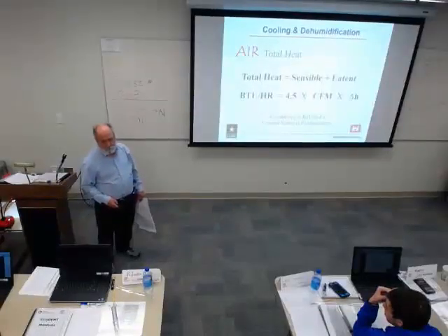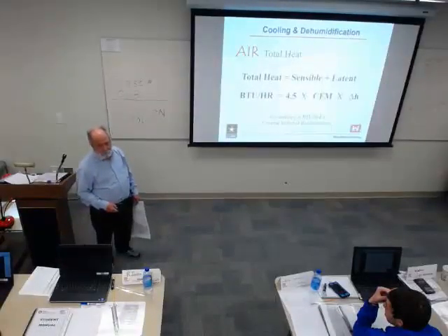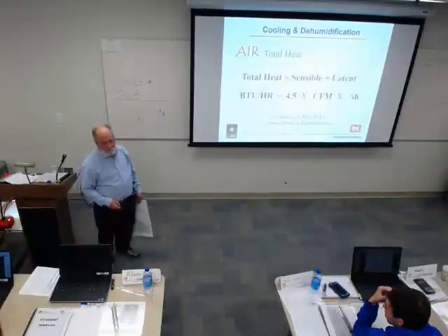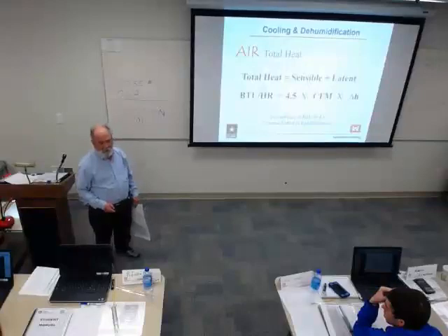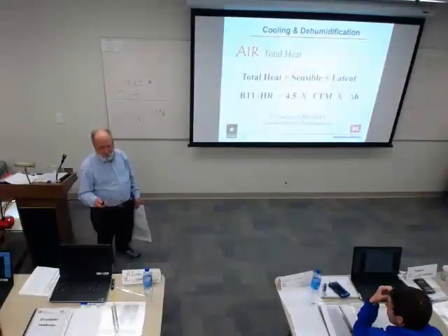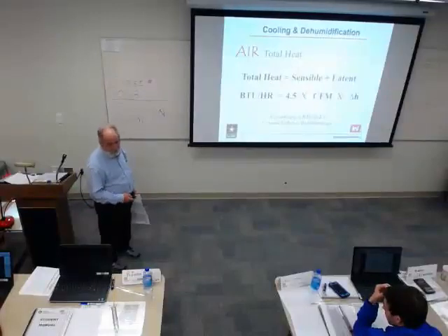Yeah. So like in the case of a dedicated outside air unit, you think about a lot of times you reject heat to the outdoors with the air conditioning system. You can actually reject some of that heat back into the airstream. That's kind of a free way, if you will, to recover that heat. Yeah. And it reduces the overall work that the compressor does too. So there are things like that. So you can use waste heat.